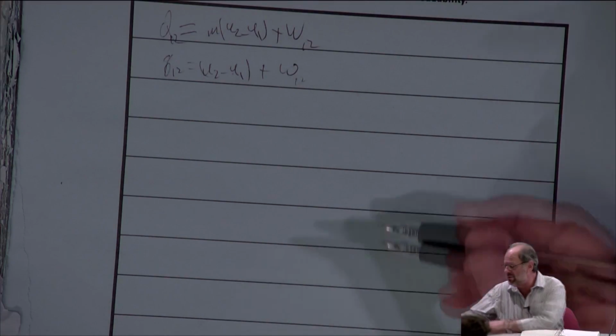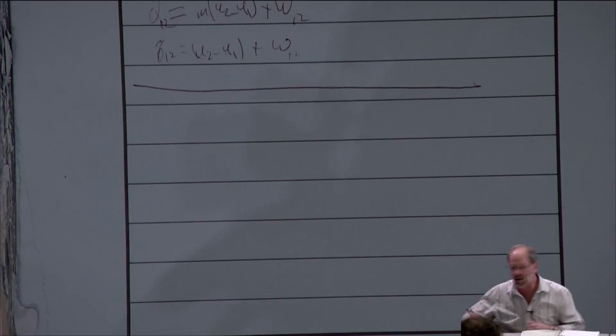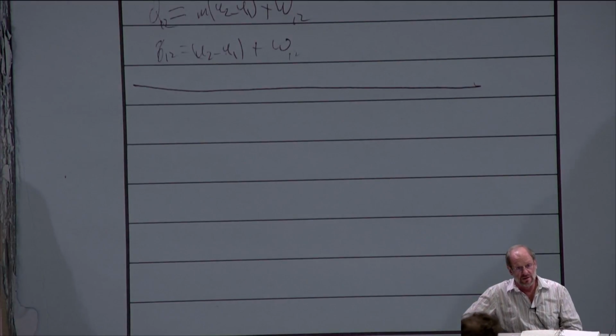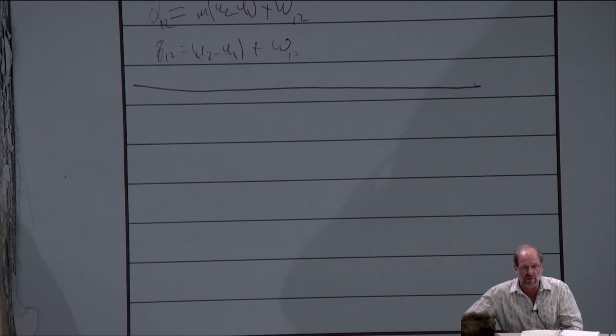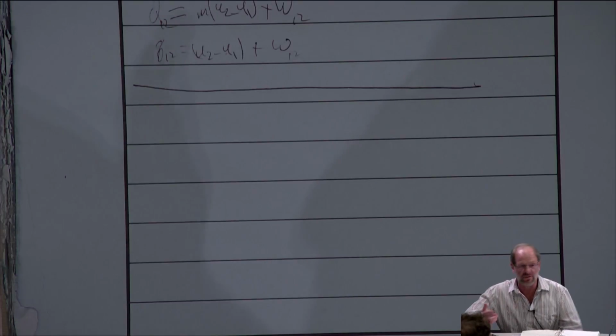We're talking now, new stuff. We're talking now about specific heats, right? Specific heat at constant pressure, specific heat at constant volume. We've seen how the specific heats are just properties, they're intensive properties, and we could use them like any other property. I know I've mentioned this before, but just because the word constant pressure or constant volume is in the title of the specific heat doesn't mean it has anything to do with a constant pressure or constant volume process, right? They're properties. You use them for whatever process you want.